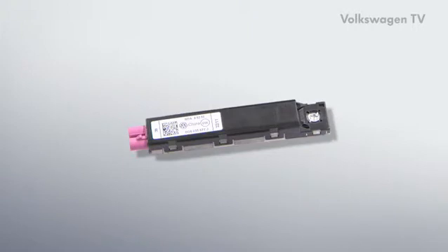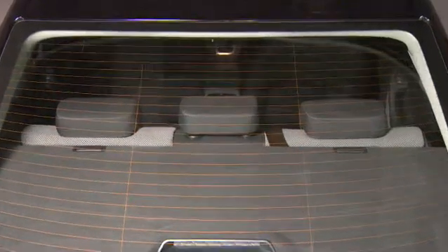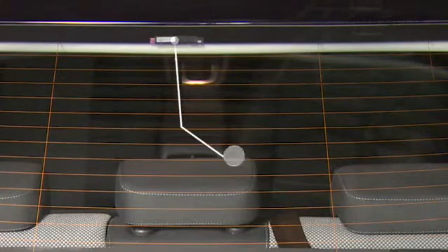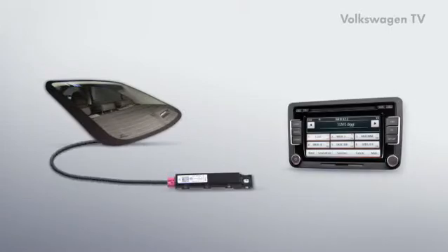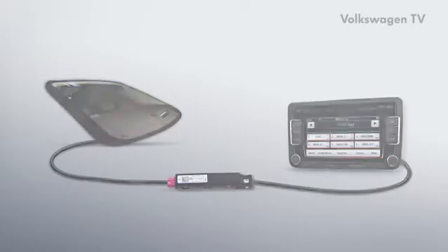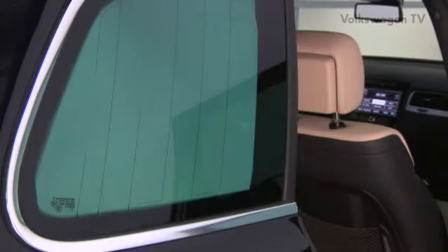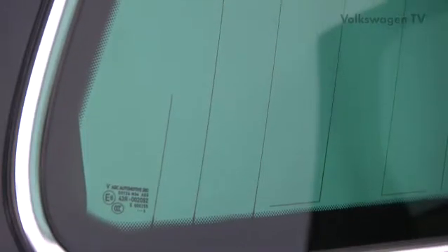The aerial amplifier or impedance transformer of the Passat, for example, is located within the upper window area. The signals received by the aerial are sent via the aerial amplifier to the radio. A side window aerial can be installed when the window is large enough and stationary. In most cases, it is attached in parallel to the electric field lines to achieve maximum field intensity.